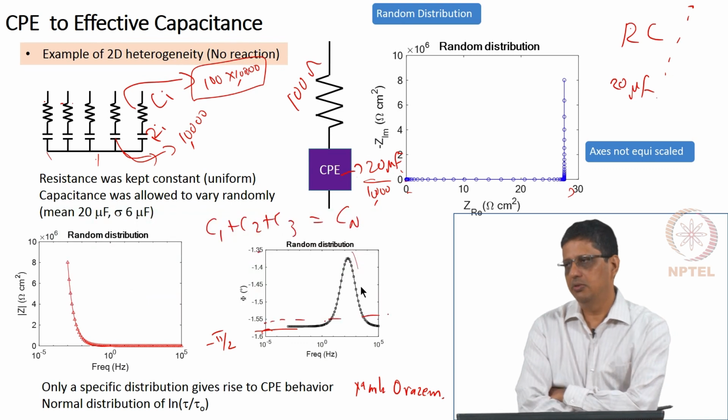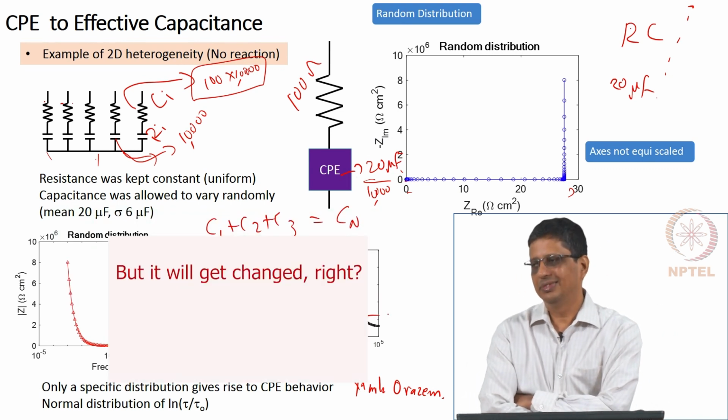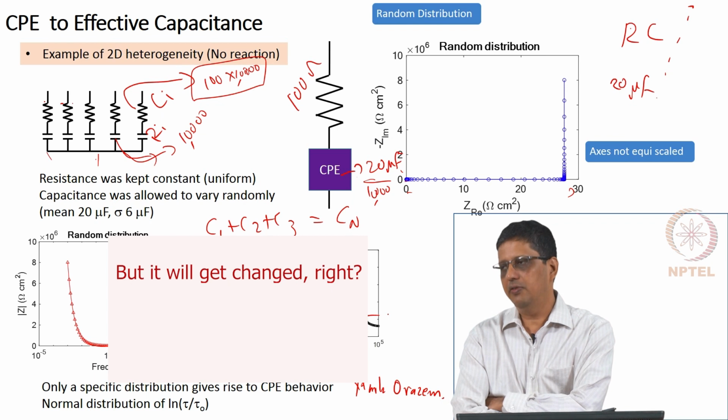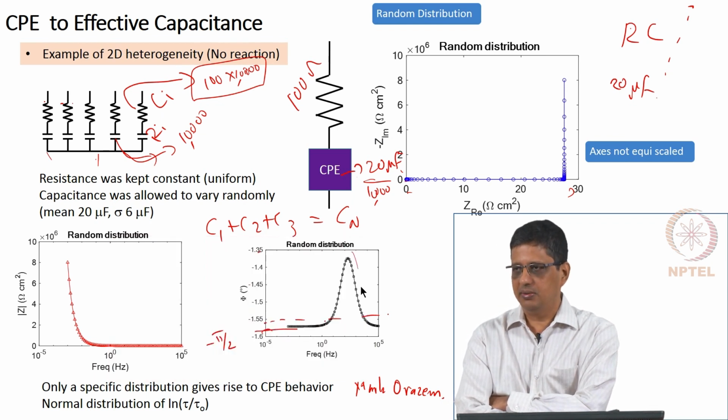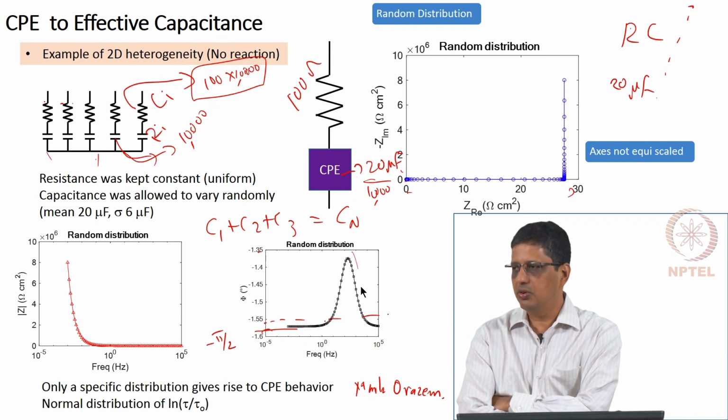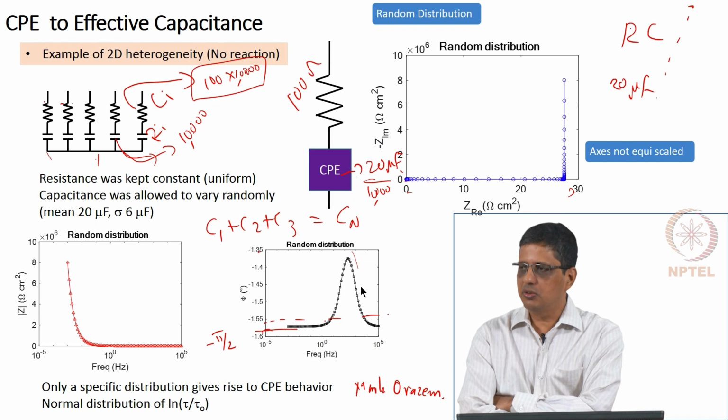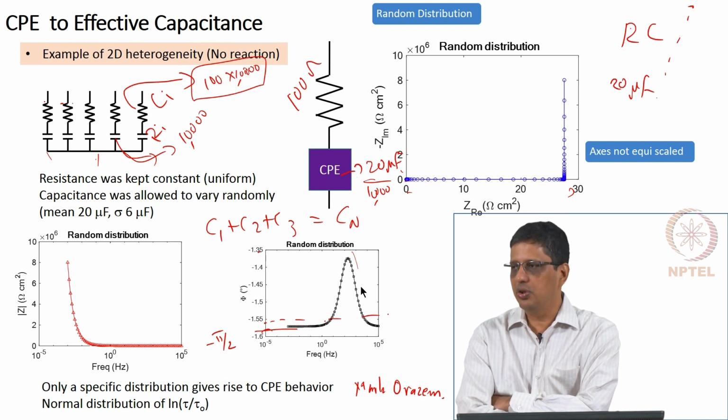Yeah, it is okay. We will get the same result. No, not very different. If you use 2 elements versus 20 elements, there is going to be a difference. If you use 100 elements or 1000 elements, you are not going to see much of a difference. I just use 10,000 because it is for sure a large enough number of distributions.